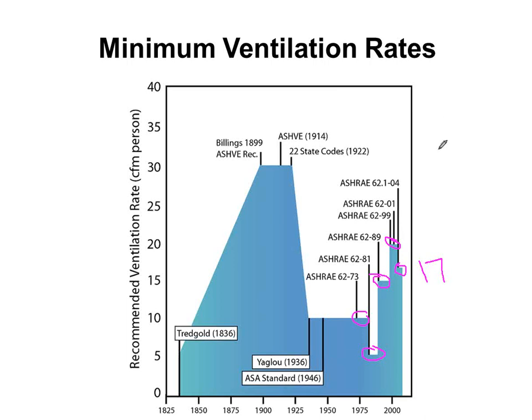So the way the current standards and codes are for office buildings, you need 5 CFM per person, and you need 0.06 CFM per square foot. You add those two numbers together to find out what your code ventilation area is. There is basically one reason why these numbers are separated instead of having a bulk number, and we got the CFM per person and CFM per square foot.